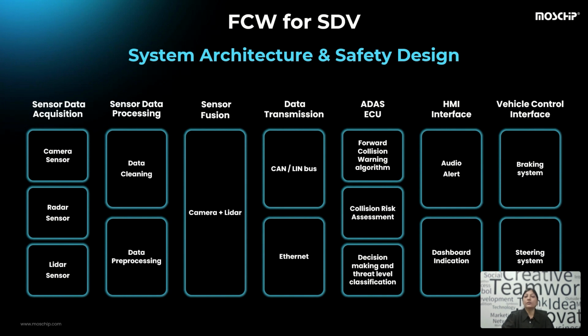Instead of shutting down the software, it adjusts the thresholds and runs on camera plus radar alone. The car still flashes a warning icon and pings the driver, but it also pops up a message: LiDAR sensor visibility reduced. In other words, the system degrades gracefully, not fatally.